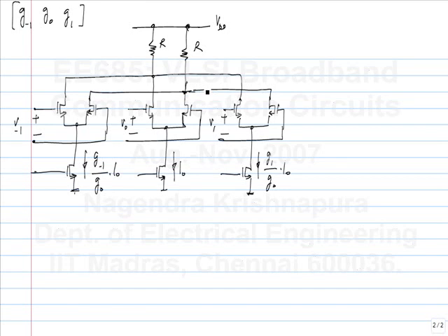What's that? Yeah, okay, that's right. So typically, we have the precursor and postcursor taps to be negative, so that we get a high frequency boost. So the polarity will be opposite to that of the cursor tap. So again, this is assumed to be the absolute value. G minus 1 by G0 is negative, but the current of course always flows downwards. The basic operation I assume is clear for this circuit. Okay.